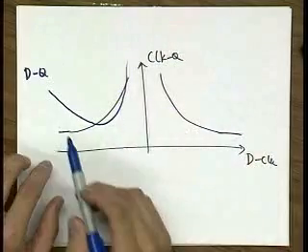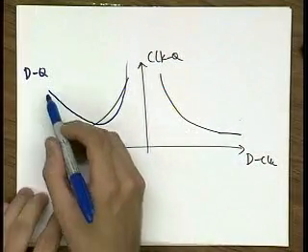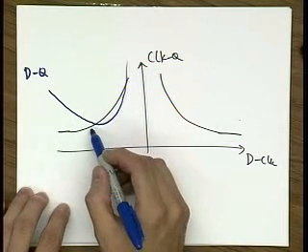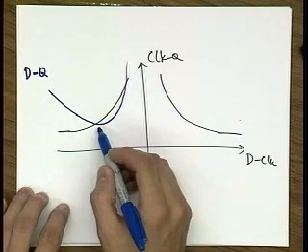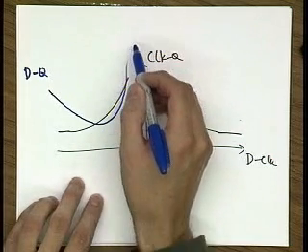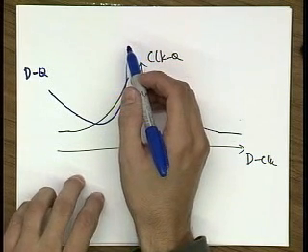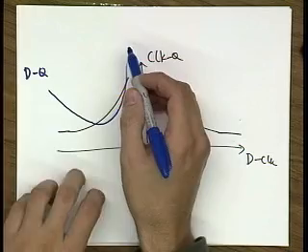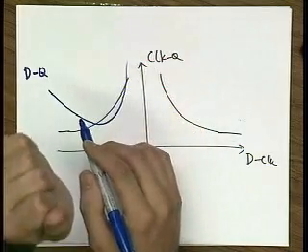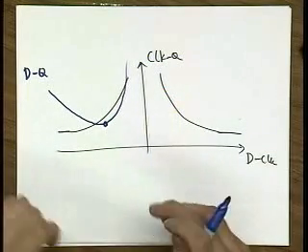What this means is that clock to Q is flat, and then I'm changing my setup. I'm moving closer, closer, closer. And at some point, when I start increasing my clock to Q, now I'm really close, that's good, but then due to the clock to Q increase, I'm going to also increase my data to Q. And really high performance designers say, well, now I'm going to give you a really precise definition of my setup time. That is really when I minimize this point, because that's the minimum delay.